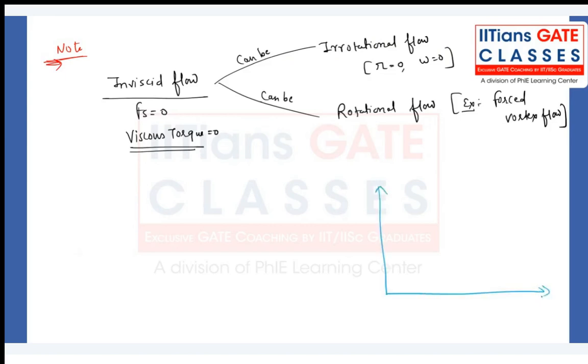What I want to say is, all three things are possible for a fluid element. A fluid element can translate, can deform, and can rotate also. See here, when you observe this fluid element ABCD, it has been translated to A'B'C'D' from here to here. They have been translated in the X direction and the Y direction both, right? That is a linear deformation rate, and they have been tilted also, not by an equal amount. So both will be there. That is a shear deformation as well as linear deformation. So here linear deformation is there.